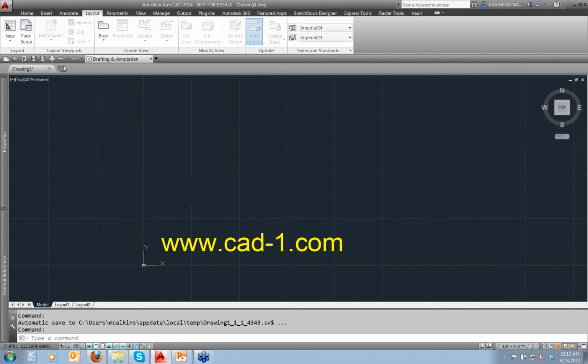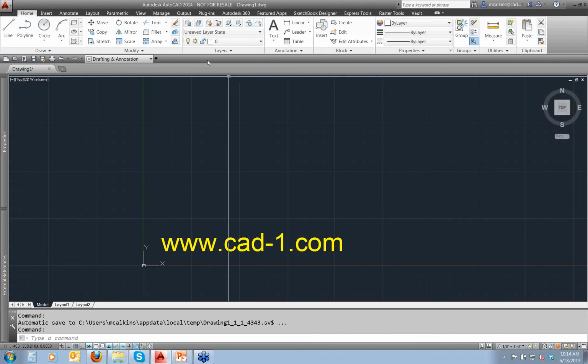Now the reason I like this is because A, it gives me just a little bit quicker access to that quick access toolbar. It's a little closer to my work area. And B, now it's opened up a whole lot of space to add tools. I can add tools to my quick access toolbar, which gives me a little bit of a hybridized workspace. Now I can have my ribbon interface, but I can still have a toolbar on which I've placed some of my more frequently used tools. If you like to create custom toolbars, now you can make one really quickly with this quick access toolbar.